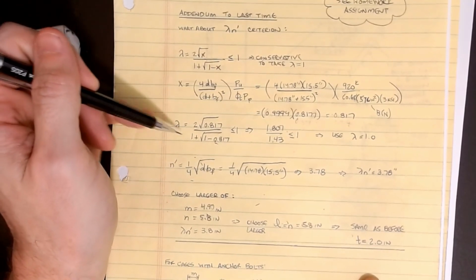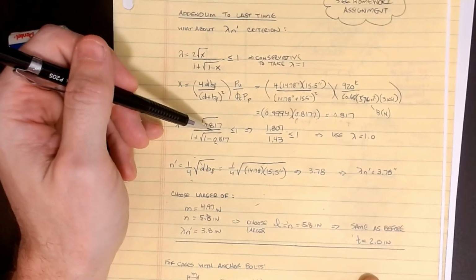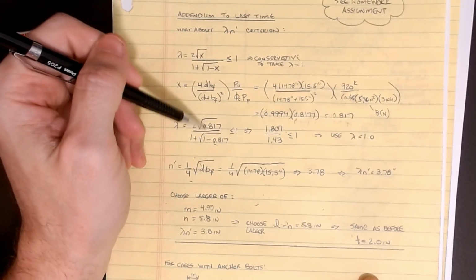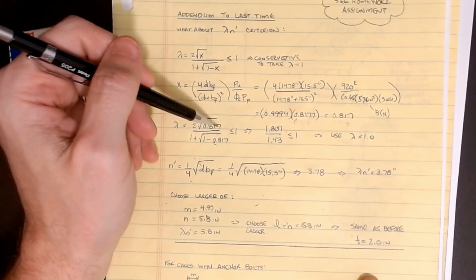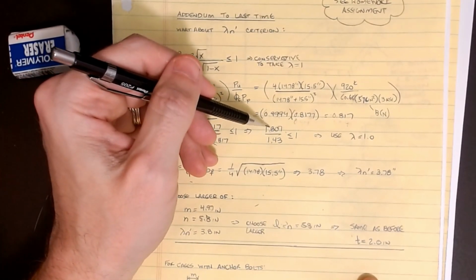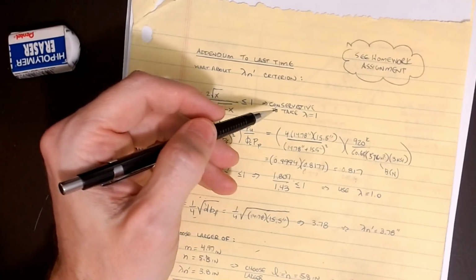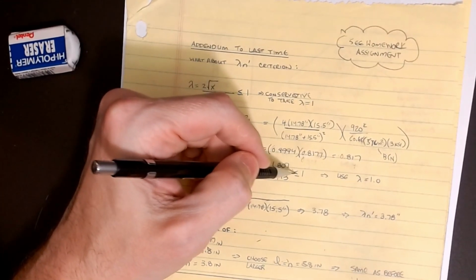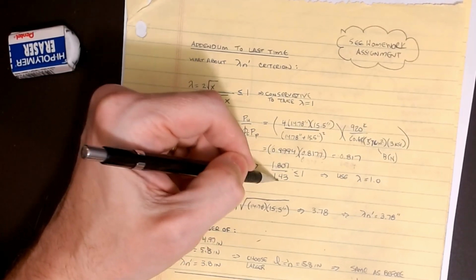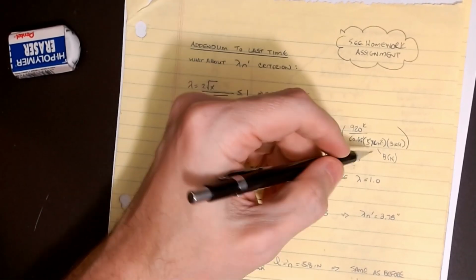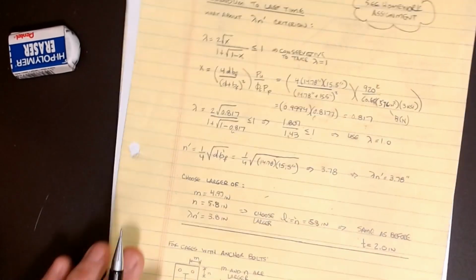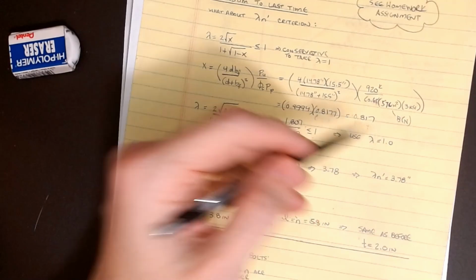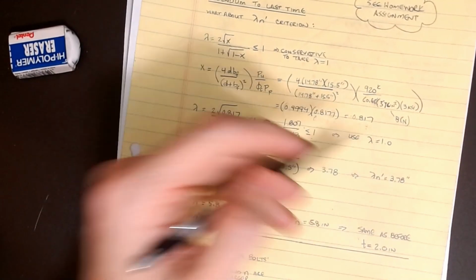So here's lambda. This is good. So we can calculate our lambda value, and you can see that 1.807 over 1.43 is what these quantities are. If this had been the 0.819, this would have been slightly larger. 1.807, okay, and so this is going to be less than or equal to 1, bounded by this. This limit is clearly greater than 1, so it didn't matter, this change that I had over there. So we're going to use a lambda of 1.0, which we could have assumed in the first place, but this proves the calculation. So we're actually using a conservative value.